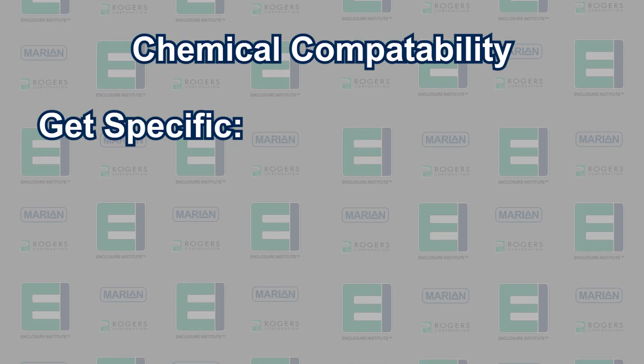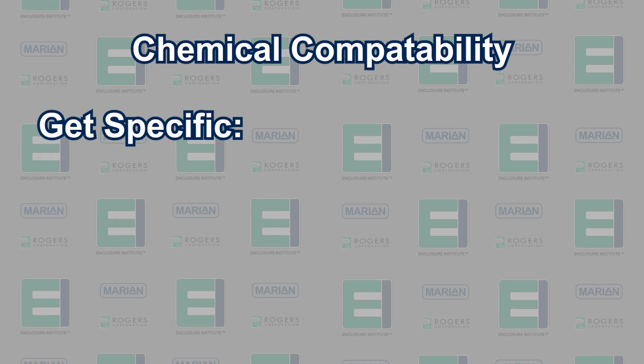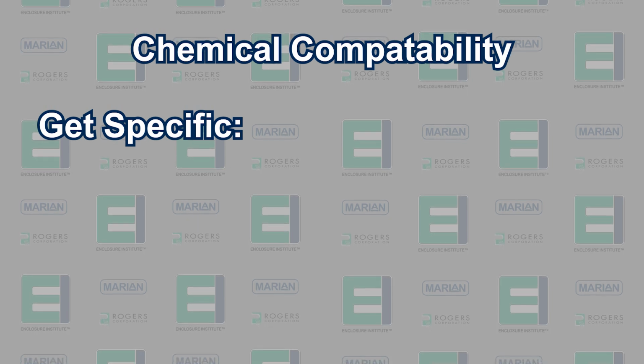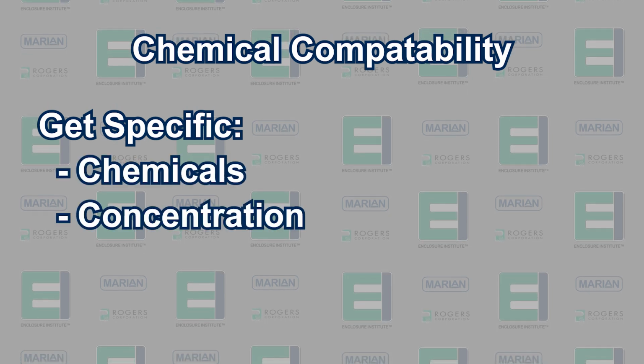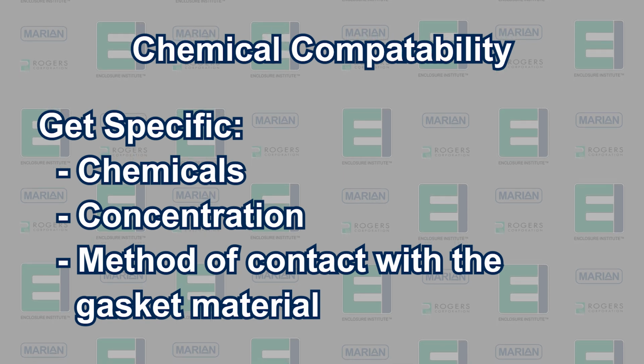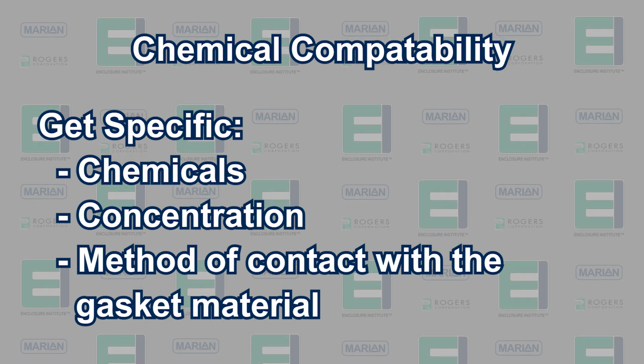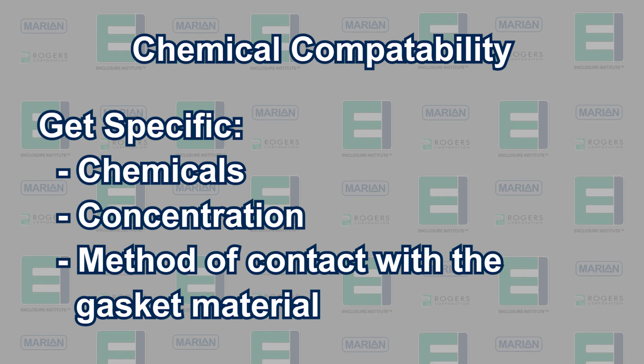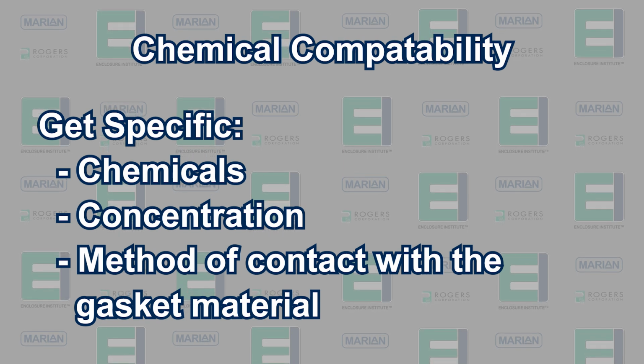But if chemical compatibility is a key concern, the best solution is to get specific. Tell us the specific chemicals, their concentration, and the method of contact with the gasket material. We can supply explicit recommendations, samples, and even in some cases, test results or first-hand evaluations.